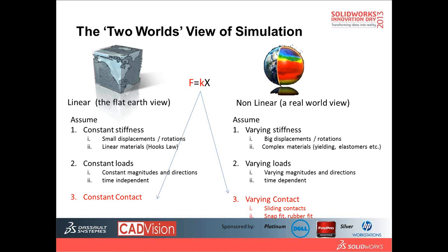One example is sliding contacts. Okay? There is this constant changing. When there is a lot of changing, usually the stress displacement relation could be nonlinear, right? For example, like snap fit, right? When the plastic is going through the locking piece, actually it deforms quite large, right? And the contacting face is constantly changing. Something like rubber feet. Rubber is very easily deformed. When we press it in somewhere, the shape of the rubber actually changes very much. Okay.